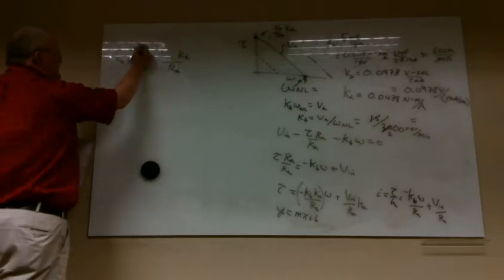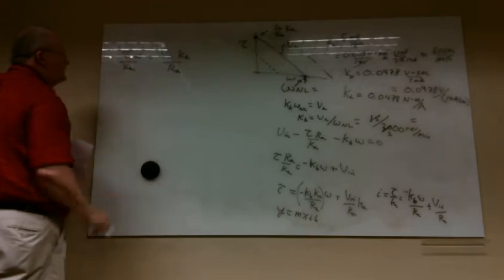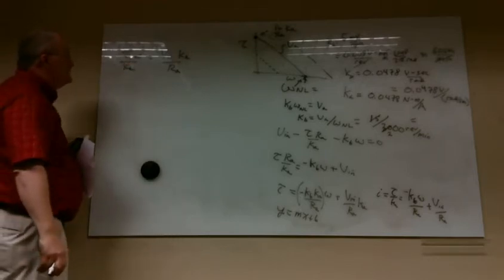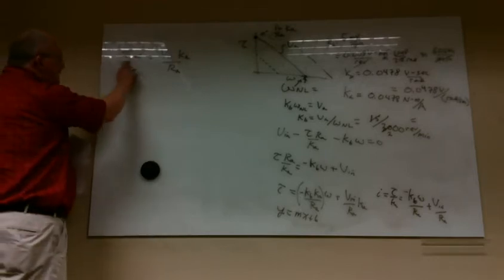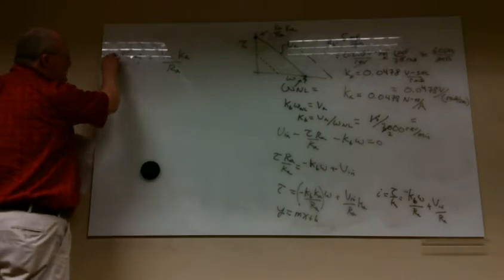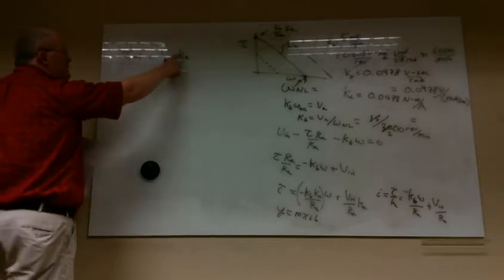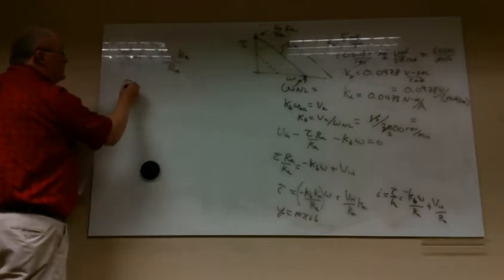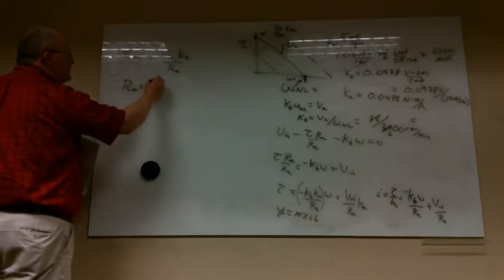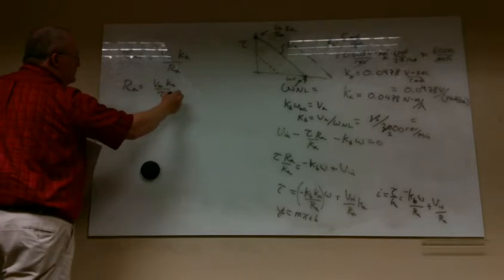This is actually going to be torque divided by K sub A. Okay, tau stall divided by K. That is, I'm sorry, once again, torque divided by K sub A is I. And so I times K sub A and all that stuff. So tau stall is V sub A K sub A over R sub A, or R sub A is equal to V sub A K sub A over tau stall. Now that's one way of looking at it.